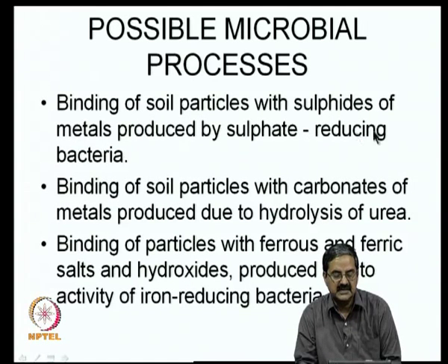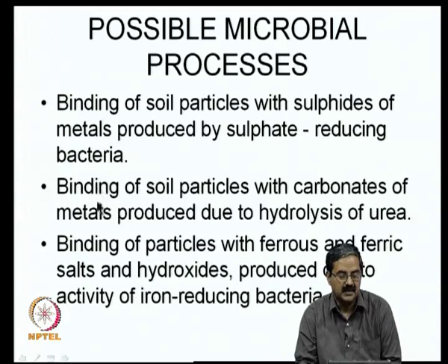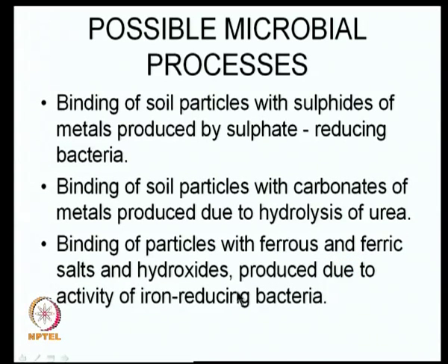Binding of soil particles with sulfides of metals produced by sulfate reducing bacteria. If you have sulfate reducing bacteria, they release sulfides of the metals, which are useful in binding. Then binding of soil particles with carbonates of the metals produced due to hydrolysis of urea. Then binding of particles with ferrous and ferric salts and hydroxides produced due to activity of iron reducing bacteria.